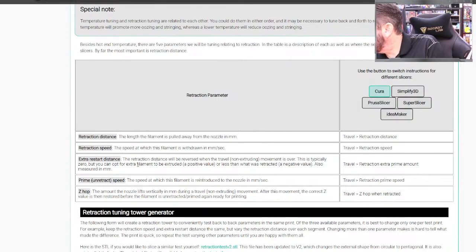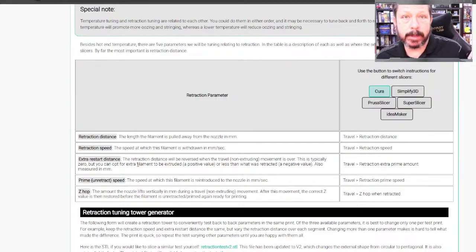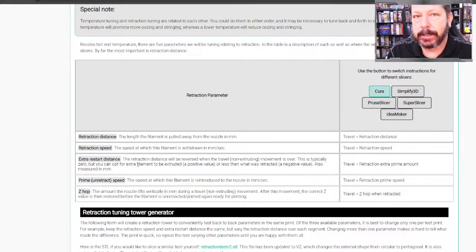Oh, all right. So you replaced your entire hot end and your secondary. Secondary meaning the part cooling fan or the one that's facing the heat sink. The part cooling fan is controlled in the slicer, so you can tell it to not be on. Maybe you printed some ABS or some material that turned it off.